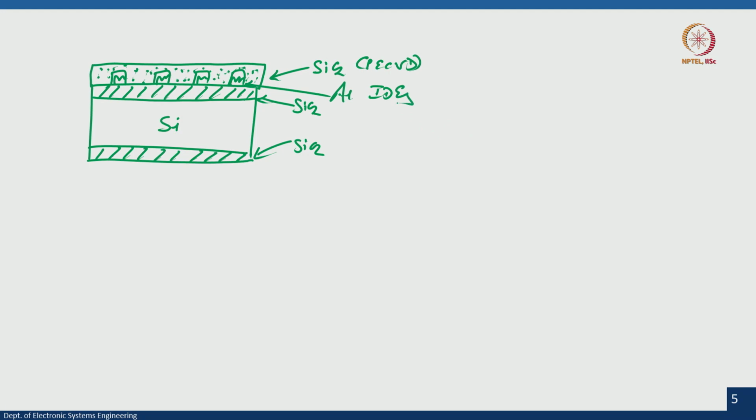So, what I will do is I will spin coat photoresist. Okay. Again I will spin coat only positive, you can use positive or negative, but I will spin coat positive photoresist. After that I load the mask, is not it?